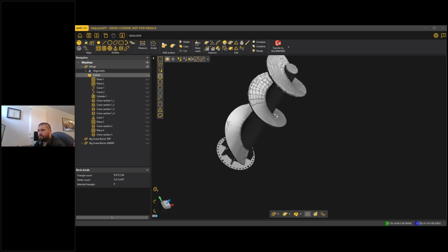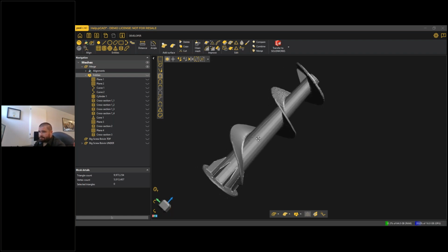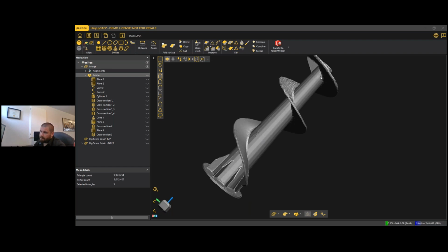talk about reverse engineering this part, most important step here would be to align it. So place the origin at the right spot of the part. Why is this important? Well, especially for a part like this, which is rotational, meaning it's going to be mounted on this side here, and it's going to be turning. Maybe at low speed might not cause any issues, but high speed parts,